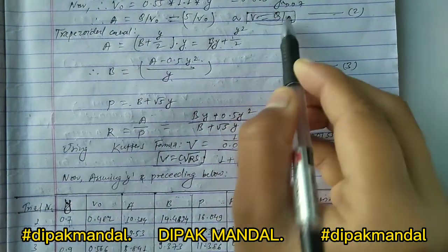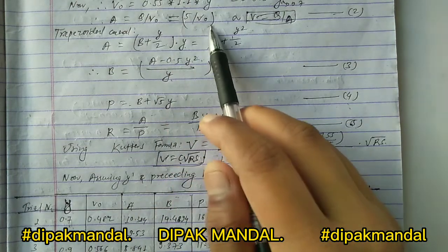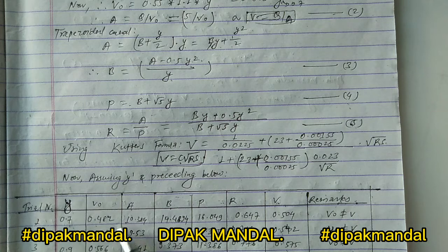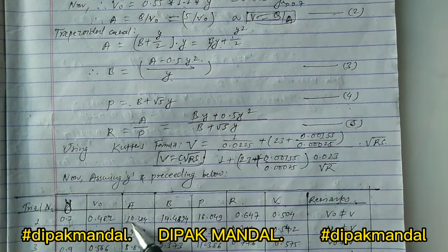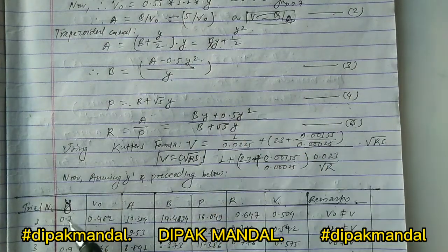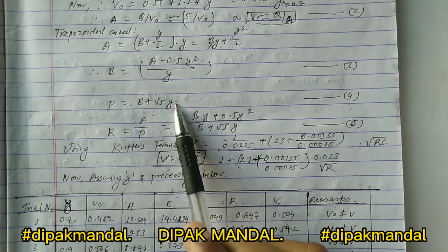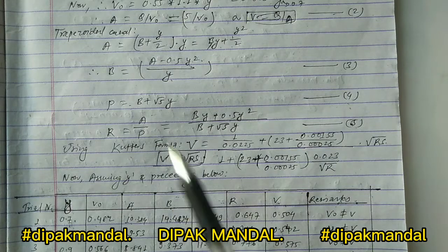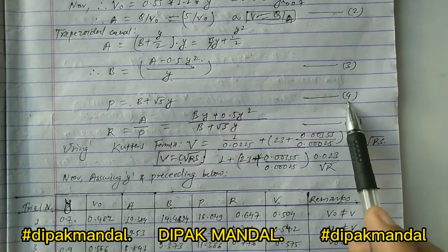I have already written this. We have to use A equal to Q by v naught, and v naught is already known, so we can simply calculate the area equal to 10.38. And B equal to (A minus 0.5 y square) by y. The value of A is already calculated, 10.38, and the value of y is taken 0.7, so the value of B becomes 14.4. Now perimeter P equal to B plus root 5 y. B is already calculated, and y is taken 0.7, so the value of P becomes, from equation number 4,